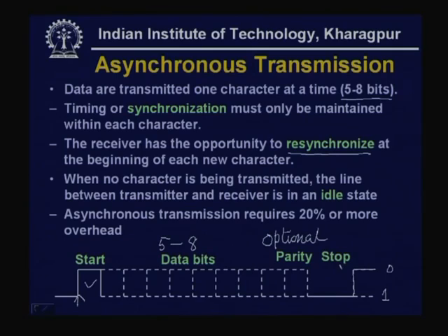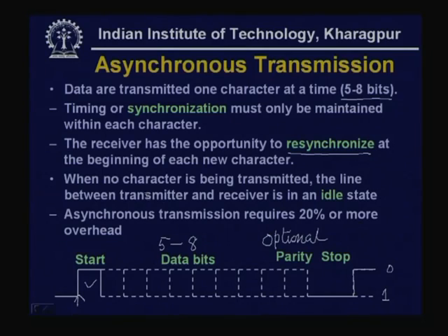Because synchronization is done at the beginning of each character, as I have already discussed in detail, the clock frequency between the transmitter and receiver need not be exactly the same. There can be a difference of about 5%. So that kind of flexibility exists here.